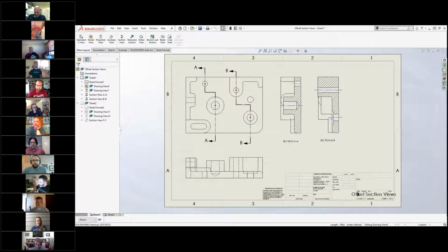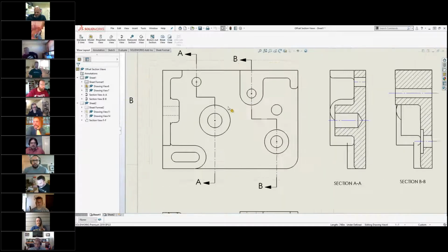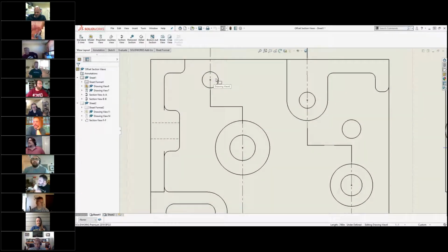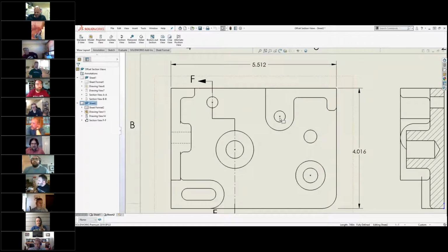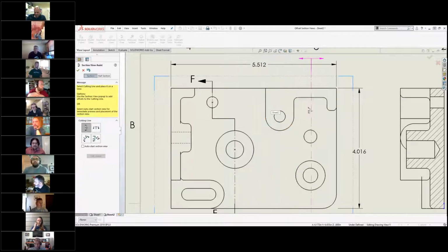What's the trick for getting that to actually add a coincident relationship to the center of a hole, for example? What you can see what I did here, and again, this is another trick from way back in the day. I just put some sketch points there, but you shouldn't even have to do that. Let me lose these points here. I'll start it here. Yeah, it knows. Watch your pointer, it'll snap.